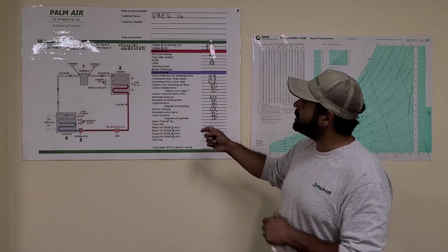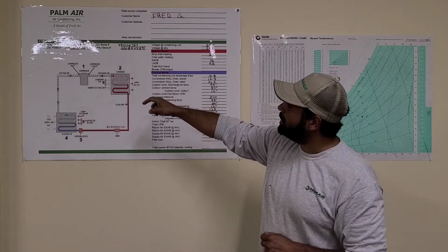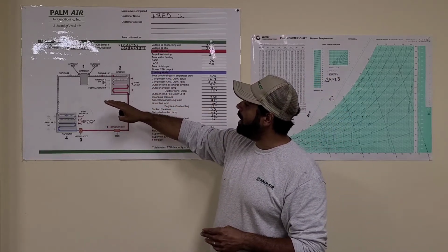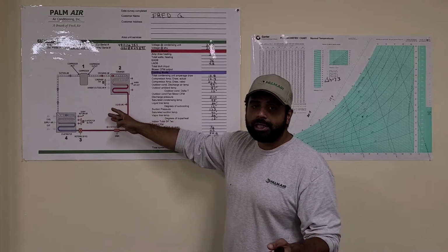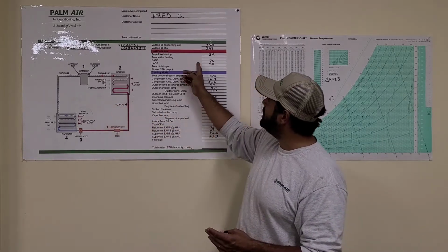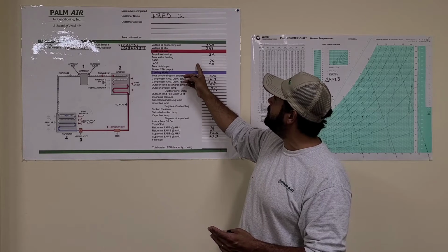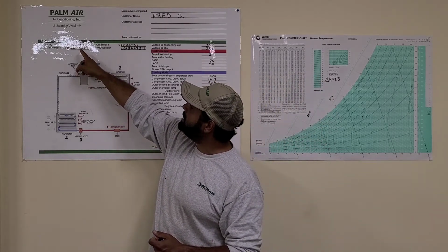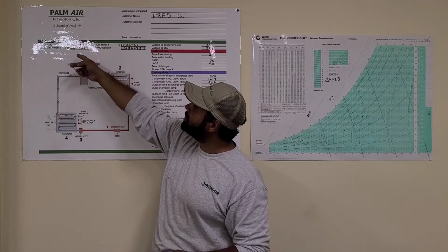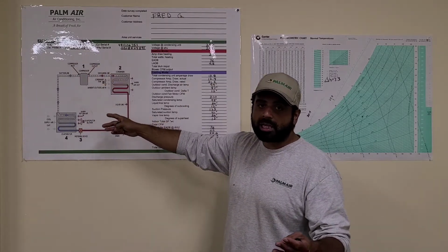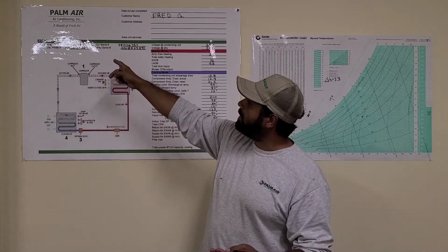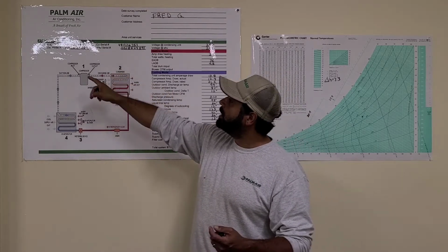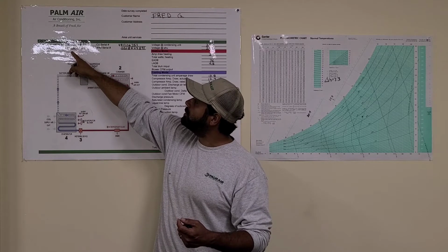We're going to start out with the type of equipment. We're in South Florida, so this was an air handler. There was no heat outside of electric heat installed into this unit, but we did put a heater into the unit, and these are the numbers for that. This is a 24 ACB 748. For those of you that aren't familiar with Carrier nomenclature, that is a 4-ton, 2-stage condenser attached to a true variable speed air handler.